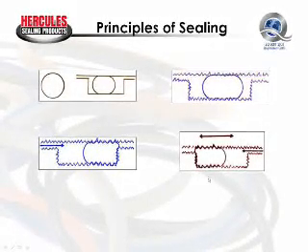So it's much more difficult to seal effectively in a dynamic sealing application like this than it is in a static application, because as this seal moves, it wants to twist and turn. And it's maintaining the stability of the seal in this groove that gives us improved sealability, especially at low pressure.